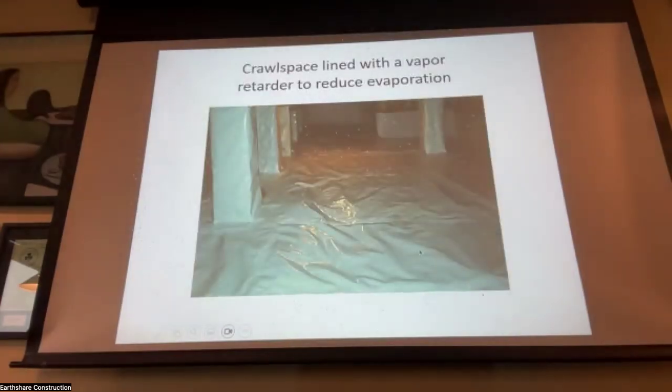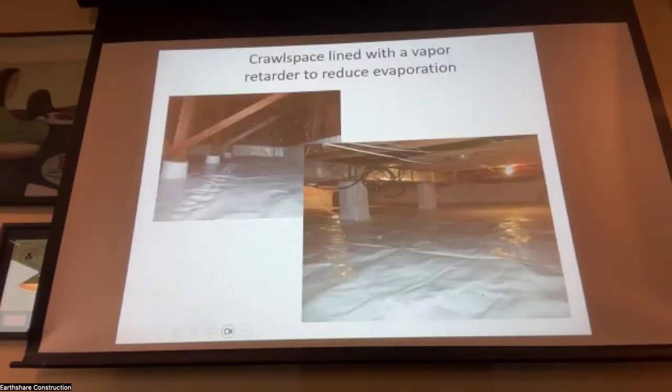So these kinds of projects, where you run the barrier not only on the floor of the crawl space or basement but up the columns, would prevent that kind of wicking up into the structure. And these are masonry, not wood. If those were wood, they'd be dead. More examples of that.